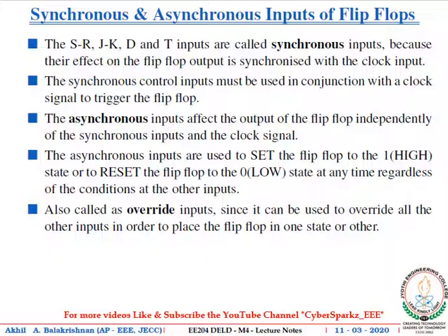Inputs of a flip-flop can be classified into two, synchronous and asynchronous inputs. Synchronous inputs are those inputs which will change the output of a flip-flop upon obtaining a triggering clock signal. They work in conjunction with the clock signal, that is, the changes in the synchronous input signal cannot make corresponding changes in the output if proper clock signal is not obtained.